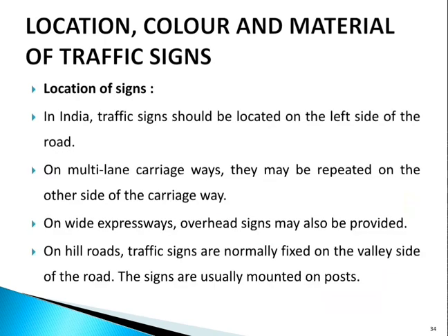Next, we are going to see location, color and material of traffic signs. The first one is location of signs. In India, traffic signs should be located on the left side of the road.